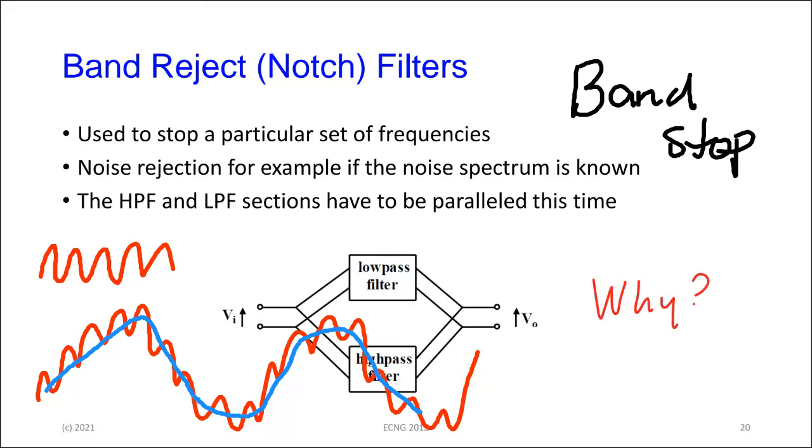And as soon as the feedback goes, it turns itself off. Or manually, somebody will look at the board that they have in front of them, and they would see that a particular frequency is suddenly getting very high amplitude on the meters, and they will just quickly put the gain down at that frequency to shut it off. That's an example of a band reject filter.